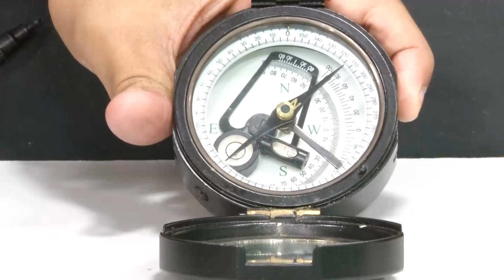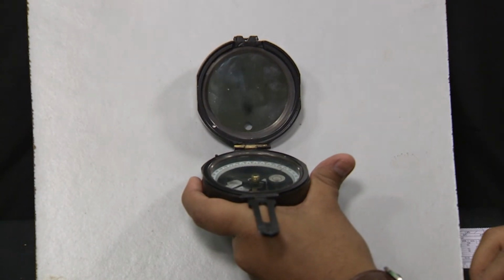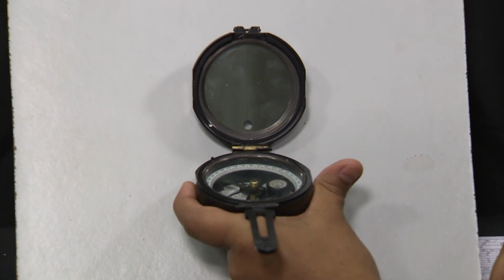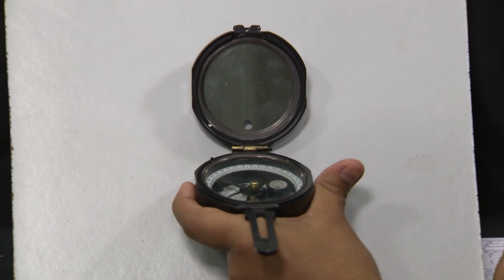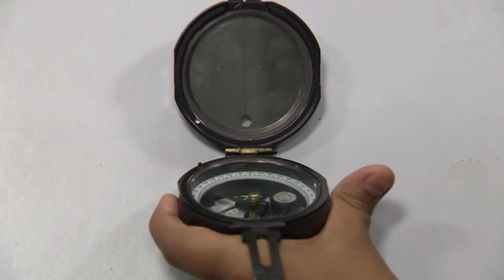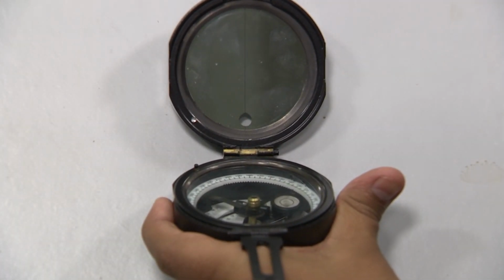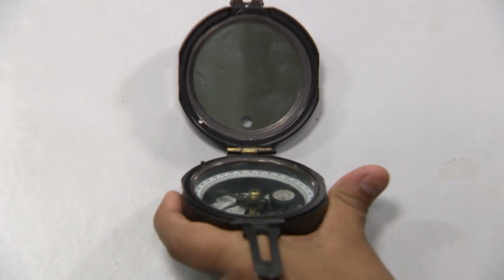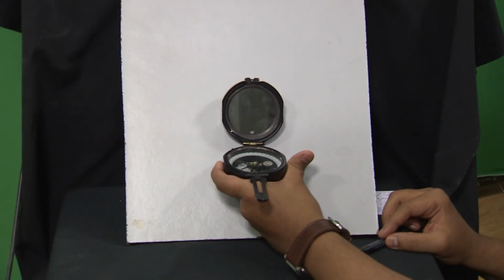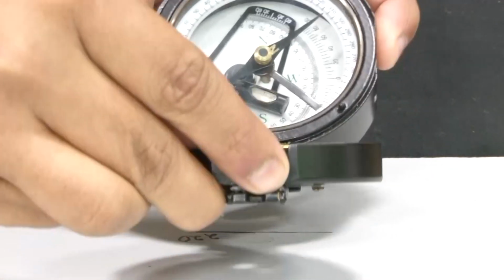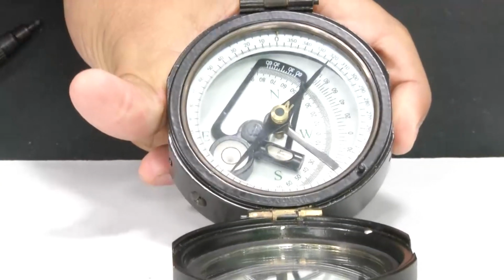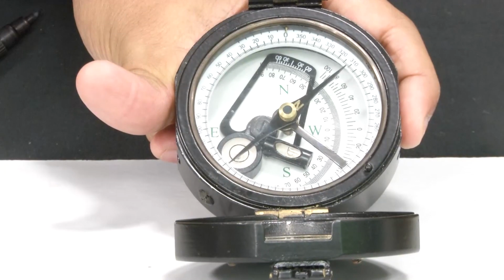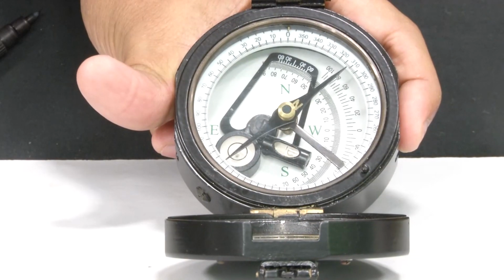So now we put this edge against the plane to measure the dip direction; the edge is placed against the strike line, and now we will measure the dip direction. As we know from the right hand rule, the dip direction would be 220 plus 90, so 310 degrees, but we would still confirm it. In order to confirm it, the compass position is this, and now we will make it horizontal. Once we have achieved the horizontal position in the compass, we take note of the northern end of the magnetic needle.